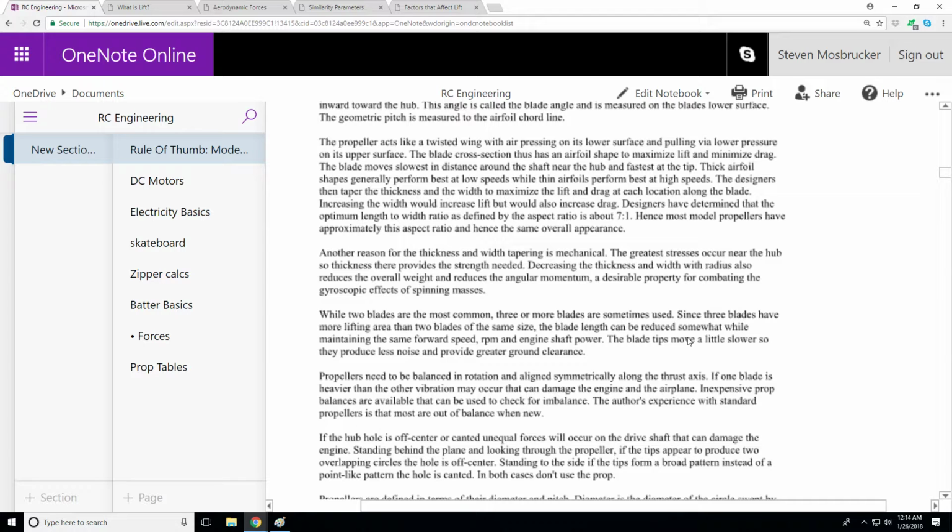And a heavier mass prop is not going to help you generate more thrust. So generally you want to minimize mass. Number one is because you have to fly that around with you, right? You have to pick up that weight with lift from the wings. And number two is you have to accelerate by speeding up that rotation.